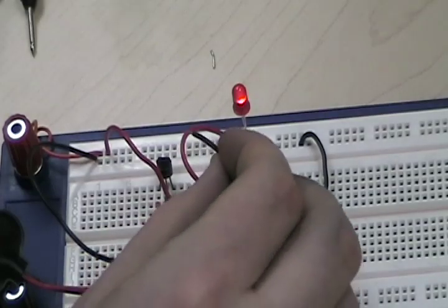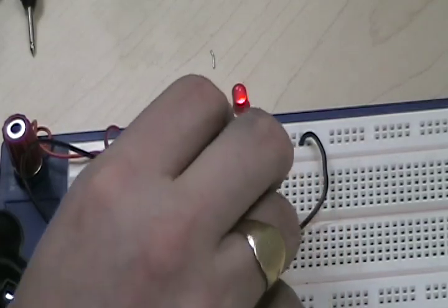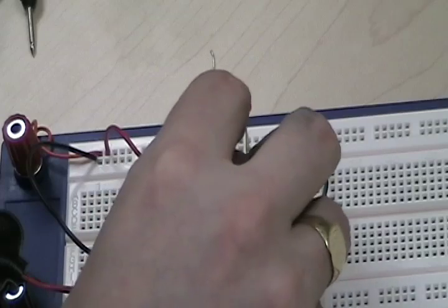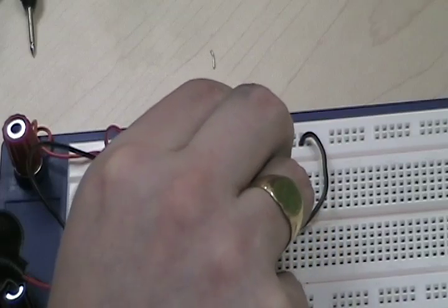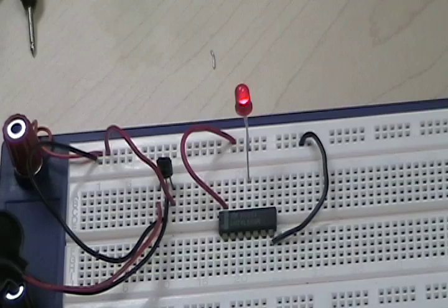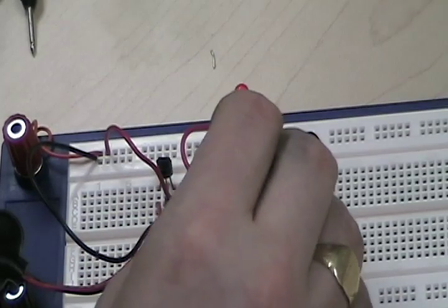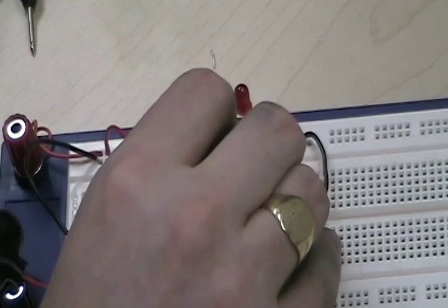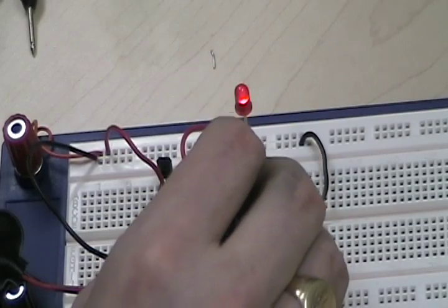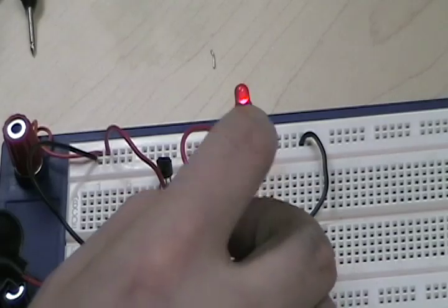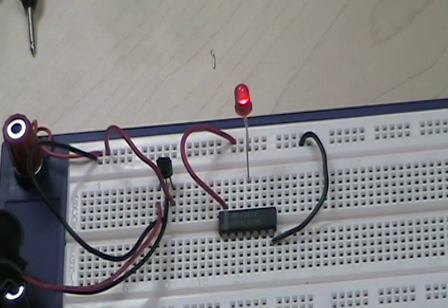So if I ground either one of these, then the output goes off. If I take it off, you don't want to leave these floating. That's what's considered floating. So that's the AND gate. If we ground any of the inputs, the output is off. Commonly, we'd have signals coming in, high or low signals, to determine the output. But for now, let's move on to another chip, shall we?